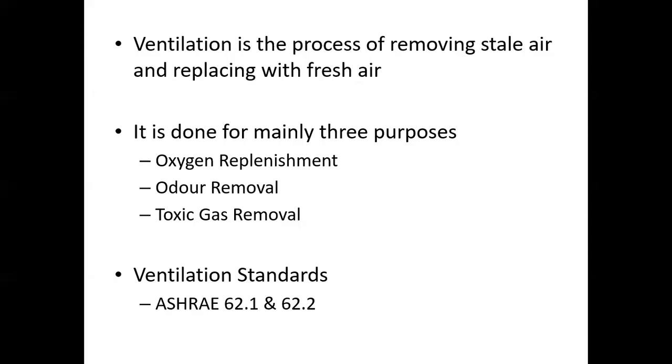Now let's discuss the negative ventilation. So in negative ventilation, we studied that here we are removing the stale air and gradually the atmosphere air will balance out, isn't it? That means it will allow the remaining fresh air directly onto the rooms itself. But for that, we need to find out the actual fresh air CFM required for those areas. So this is not meant to be the rooms or anything. It's purely meant to be toilet areas and similarly underground areas like the tunnels, basements, car parking areas, and probably the factories.